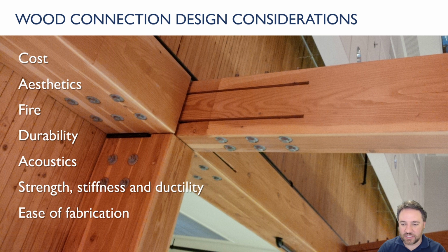So there's a lot of ways that we can do concealed connections like that. Fire is a big consideration. We're not going to talk about that explicitly here, maybe in a shorter lecture in the future. But one thing that it might be interesting to know at this point is that having exposed steel in the connections can actually be something that governs for fire design.